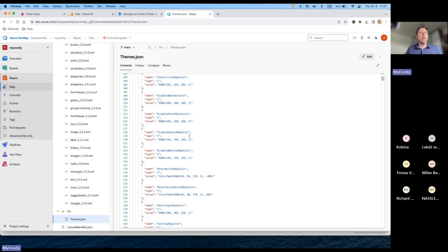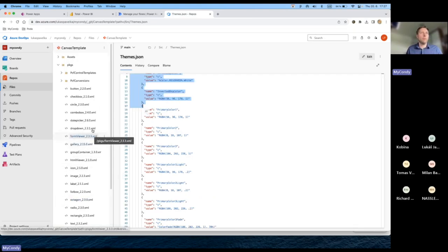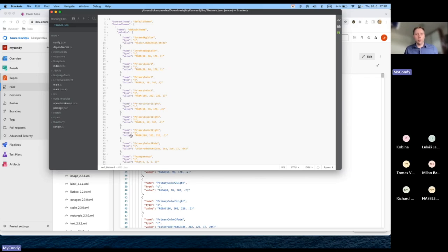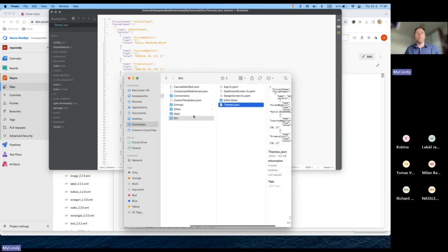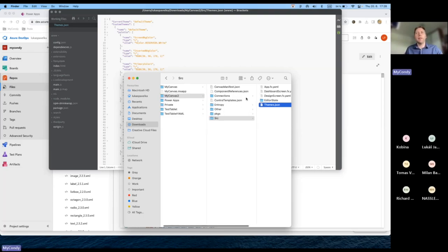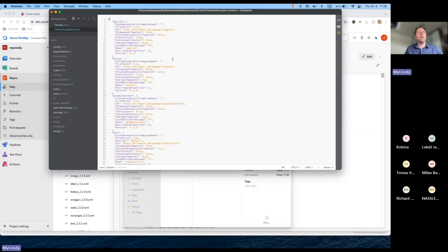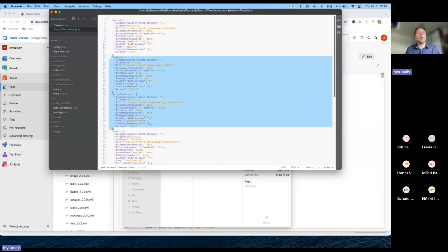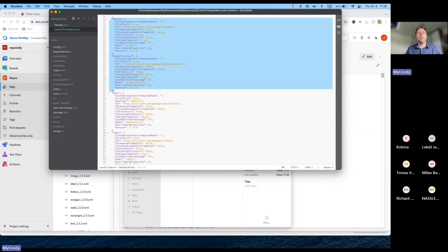So this is the place to look if you have an error. And the last thing that is important for the Canvas application, when you are putting in many more graphics and components to the template, is the control templates. Here you can find all the components which are recognized in your MSAPP file. For example, in my template, you saw that I used only button and label.